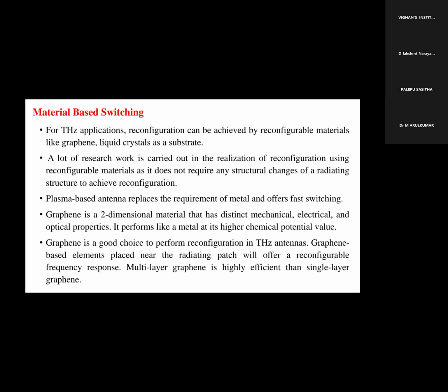Graphene is a two-dimensional material that has distinct material, mechanical, electrical, and also optical properties. It performs like a metal at a high chemical potential value. Graphene is a good choice to perform the reconfiguration in terahertz antennas. Graphene-based elements placed near the radiating patch will offer a reconfigurable frequency response. Multi-layer graphene is more efficient than single-layer graphene. Thus, the miniaturization is inversely proportional to the efficiency.